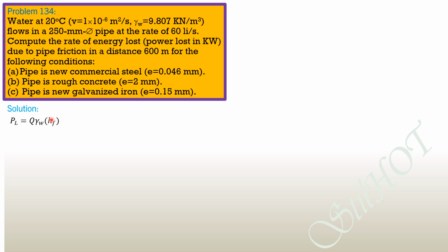So it's really the friction factor that matters here to solve for this power loss, where friction factor is solved by using Colebrook equations, and velocity is 4 times discharge over pi diameter square. So this is the formula by Colebrook if the pipe behaves as a smooth pipe.